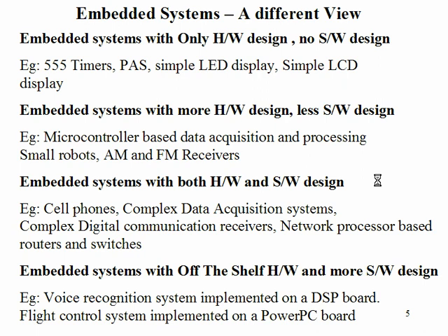Got the point? See, what MATLAB will do, I'll tell you. Let's say you are using MATLAB to write some code, and you are compiling that MATLAB code and putting it on a DSP processor. The MATLAB tool in the backend is able to convert the MATLAB script into C code or equivalent assembly code that is ultimately placed on the DSP processor which is running. You got the point? So no DSP processor in this world will directly run the MATLAB script like that, because they are ultimately designed to run machine code, again similar to your general purpose processor.